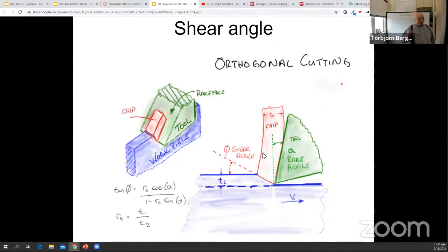And you can do that with your calipers to measure that chip thickness. So if you know what the rake angle is, and you know what the feed rate was and the side edge cutting angle was, you can determine what the shear plane must have been. That's kind of cool, I guess. Why do we care what the angle of the shear plane was?